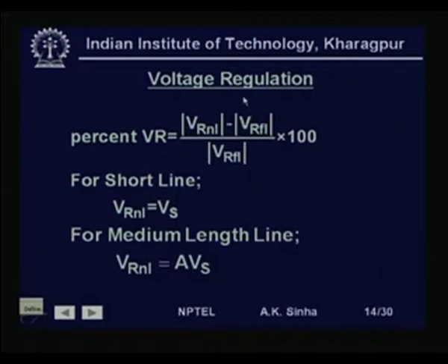transmission line. So, this percentage voltage regulation gives us a very good parameter, because when we are designing a transmission line, we cannot allow more than about 8 to 10% voltage drop. So, voltage regulation will tell us what is going to be the voltage drop when the transmission line is fully loaded, because if the voltage drop is more, then we need some compensation.